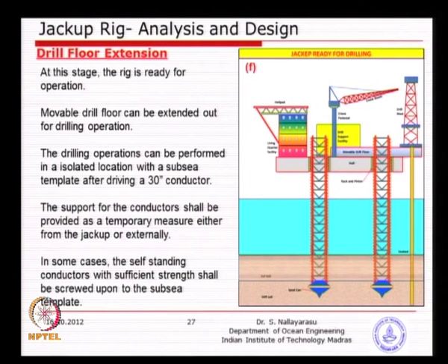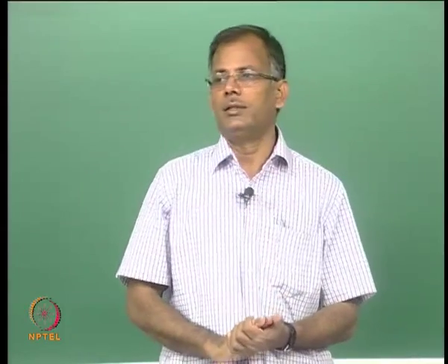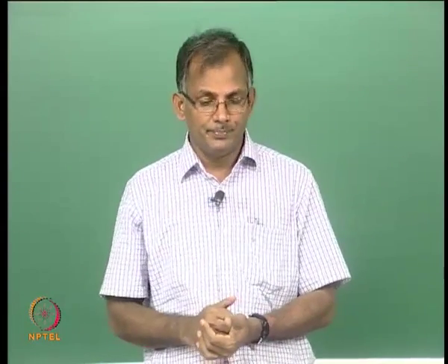So, that is why, when doing appraisal drilling or drilling before the jacket structure is constructed, you have to be careful with how you are going to do the drilling. Once the jacket is there, then you do not need to worry, because you have several supports for the conductors at the jackup jackets.